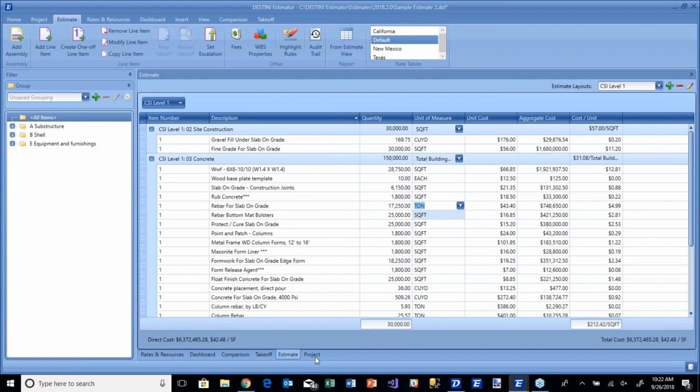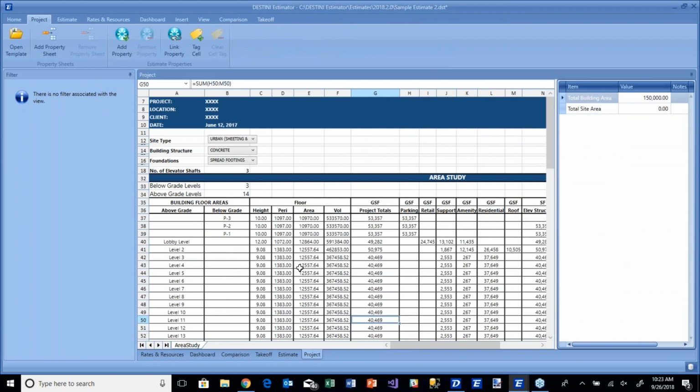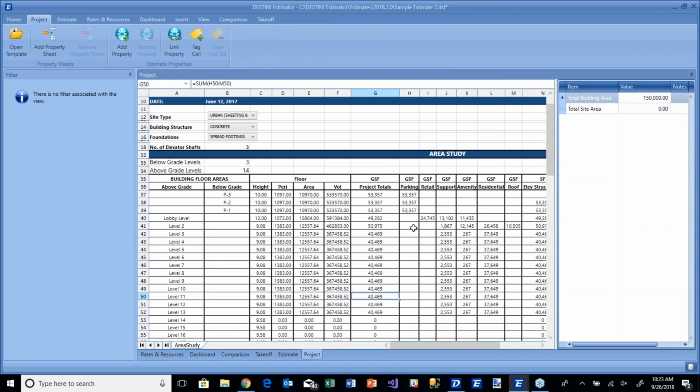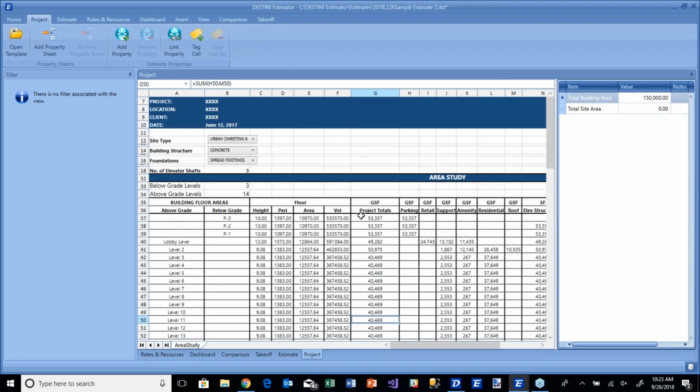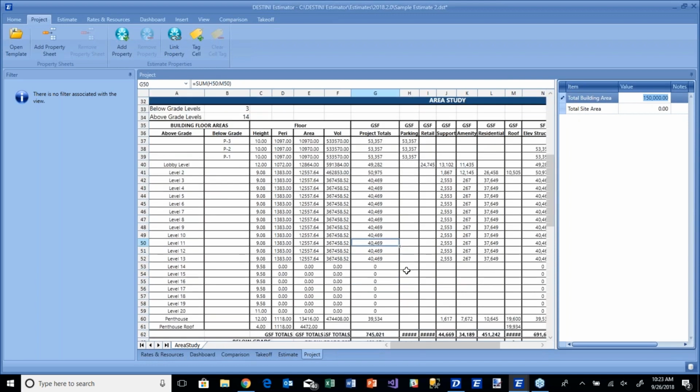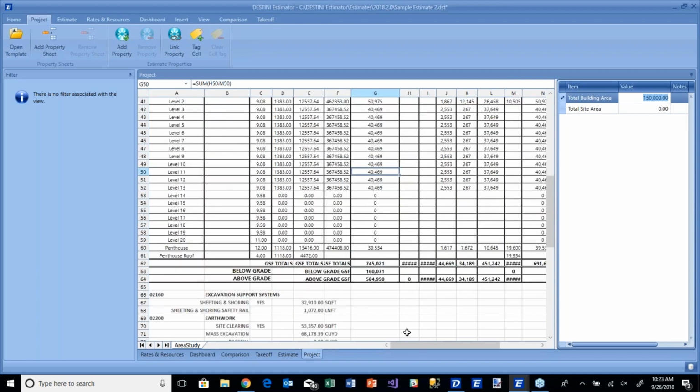So you can effectively, especially if you've got multiple monitors, have that up, you can effectively hard code or hard key your total overline quantity to whatever value you want. If you want that to be a static value, you can. Or if you want to make it a little bit more advanced, you can actually drive this value from the values inside of this Excel spreadsheet, which is, again, embedded in the application now. So this could have as many tabs as you want. Right now I've only got one tab. We call it area study, so it's just a high-level area study of the project. But I could, if I wanted to, drive my total building area based off of the total building area calculated by the spreadsheet.